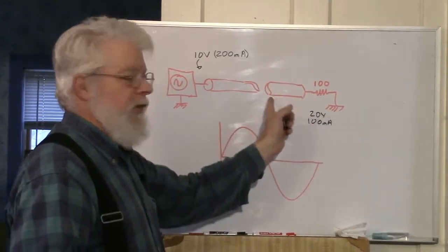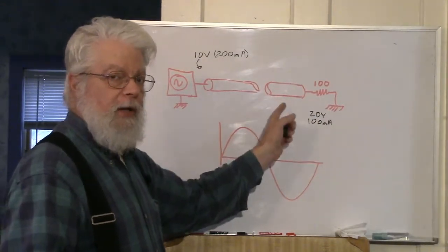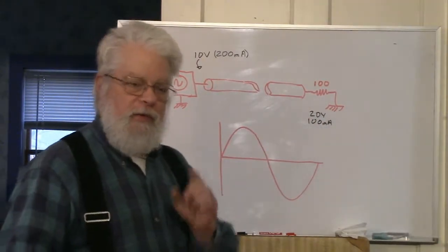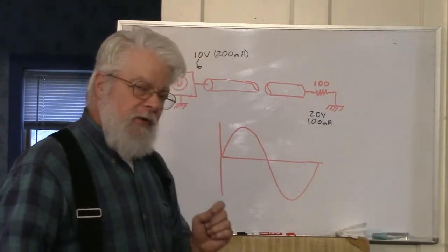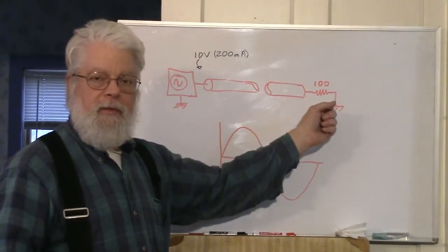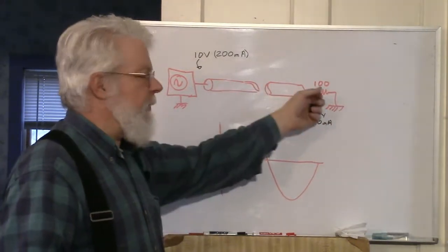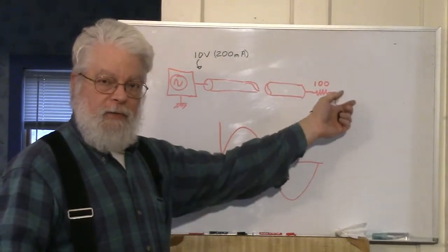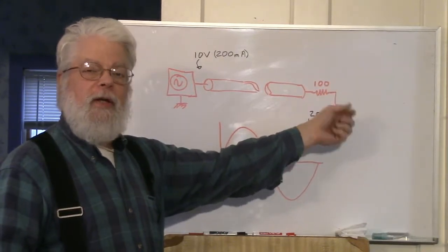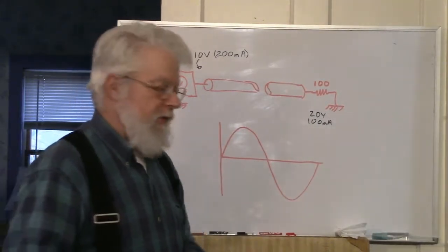If the terminating impedance is raised above the characteristic impedance, if it's too high, the voltage will rise. And this is the interesting part: that has virtually the same effect as inserting a signal generator at the load end. So this excess of current producing an excess of voltage across 100 ohms is going to be as if a signal generator has been turned on and is sending a voltage back. The backward wave, as they say.